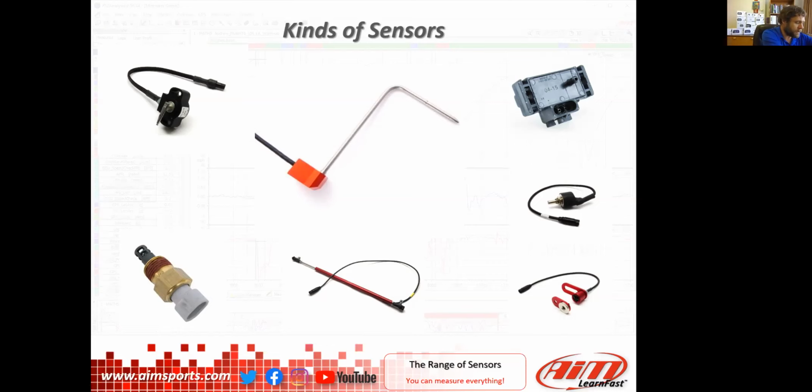We have pictures on there of the rotary sensors, where the sensor gets hard mounted and then gets moved around the center axis in a rotary way, and it can be used for a throttle position. On some cars, this could be used for a suspension bell crank movement. Another rotary kind of sensor is the gear type. I used these 20 years ago for steering positions because you can put a little pulley around it and turn it.